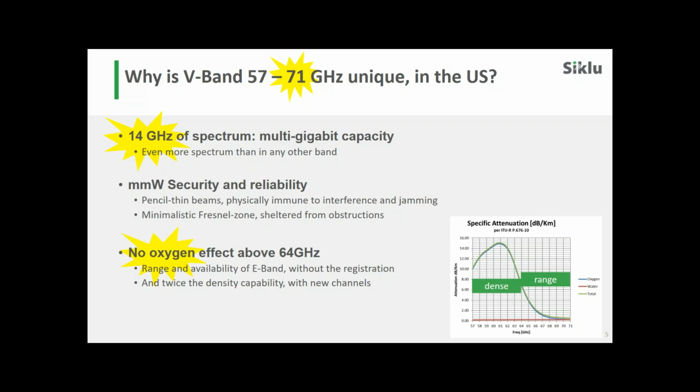Another question here, back to the PoE. If you connect a device which can deliver more power than the radio needs, there is a negotiation built into the PoE layer 1, I would say, whereby the PD device, the radio in our case, will tell the PSE device, the Ethernet switch or standard power supply, what it needs in terms of power, and in that case the PSE will, if it can, deliver that amount of power.